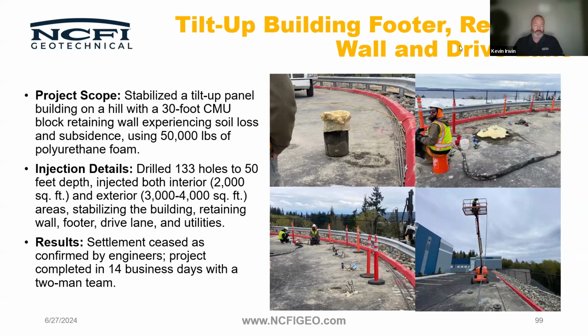But in that case, no, that's not something that I've been concerned about typically, unless, if you do hit an unknown void, and it's a big void, you can end up with an exotherm issue. But typically underground, you're not running into those situations. If you hit a pipe, you're going to know it, and you're filling up a pipe. Your customer or their neighbor is going to be coming out to say, hey, my toilets are stopped up or whatever. Or smoking.